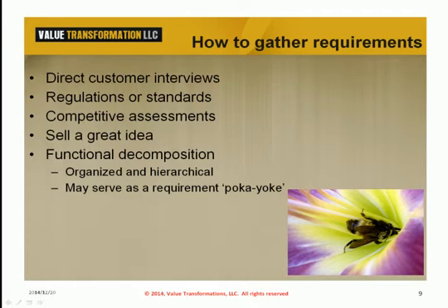If our product is particularly complicated or a collection of systems, we may choose to approach the task by starting at the top level, defining the system and decomposing the specific subsystem interactions required to deliver that system. We decompose the highest system functions, and this decomposition leads us to the requirements of the subsystem and components within that subsystem. We can diagram this breakdown using the Functional Analysis Systems Technique, or FAST, an industry standard for value engineering.